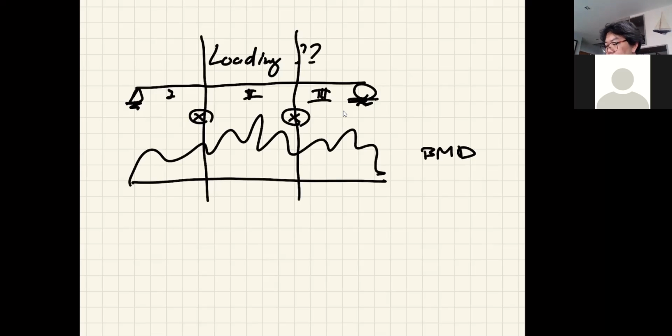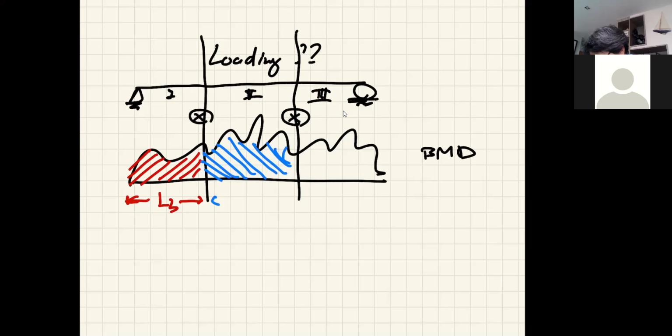And when you investigate your region number 1, this is your bending moment diagram, because this is your unbraced length number 1. So you divide this into 4 equal parts, so you get your MA, MB, and MC, and then M max. And then you move on to your second region, and you investigate this with another LB, divide them into 4 equal points, calculate your CB, and go on. And then the third region, it's the same thing, right?